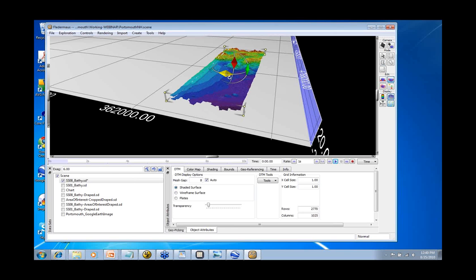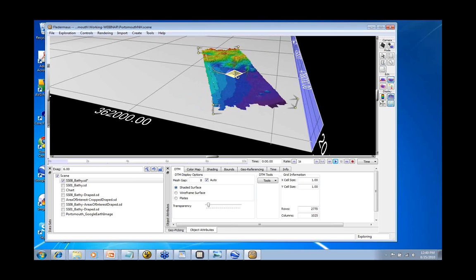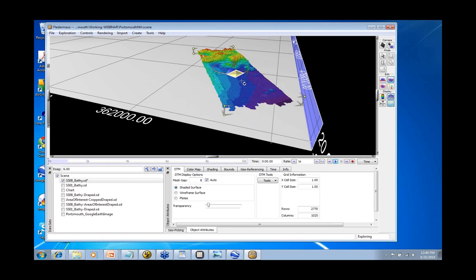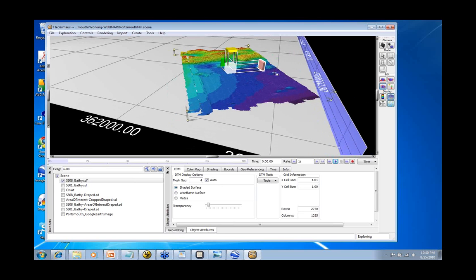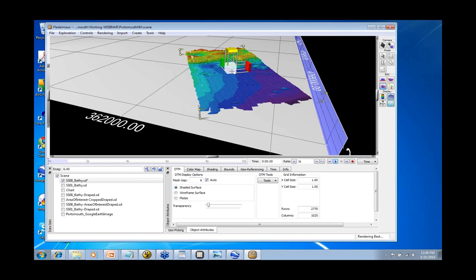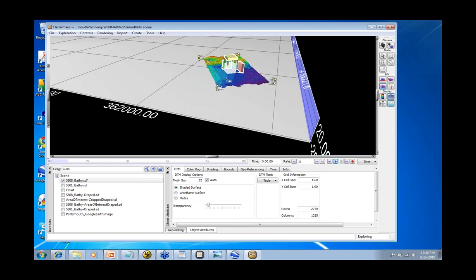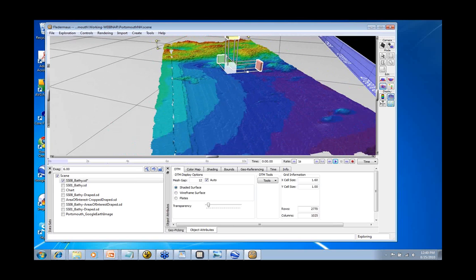Rotation gives you a rotation axis, and again, you left click on the axis you want to spin in, and you can turn, and it lets me spin it all around. And scale will let you scale in any direction or in all. So if I click and drag on this red plate, it will scale in one direction. If I click and drag on the white center bit, it scales in all directions.